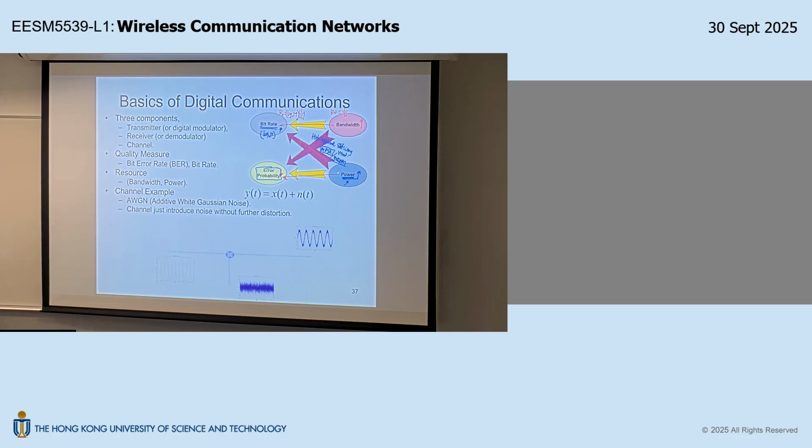The reason, which we'll talk about later on, is that a cellular network is an interference-limited system. For the same reason, if you want to use 4096 QAM in a cellular network, you need to make sure that the signal-to-noise-plus-interference ratio is very large. However, that's why I said it's an interference-limited system.